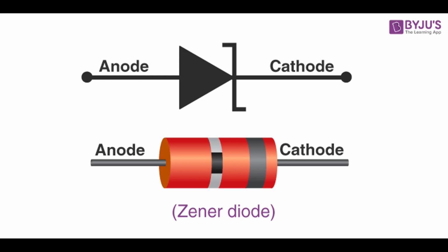Clamping. Purpose: clamping is used to shift the entire waveform to a desired DC level or voltage offset while maintaining its shape. Circuit configuration: in a diode clamping circuit, a diode is connected in parallel with the input signal, and a DC voltage source, the biasing voltage, is used. The diode conducts when the input signal goes below or above the biasing voltage, effectively shifting the entire waveform up or down. Types of clamping.